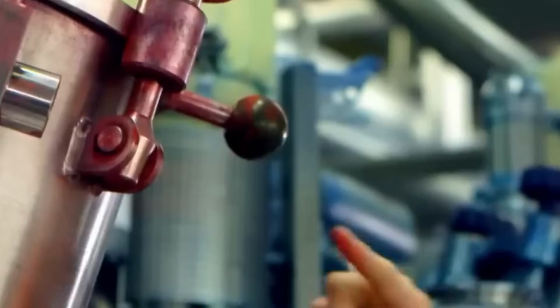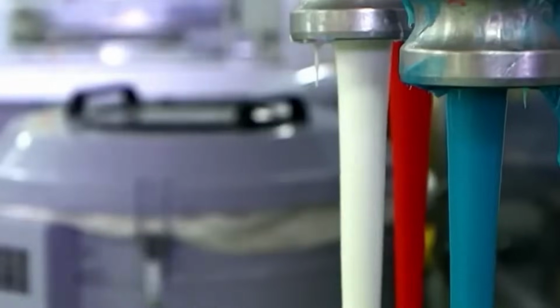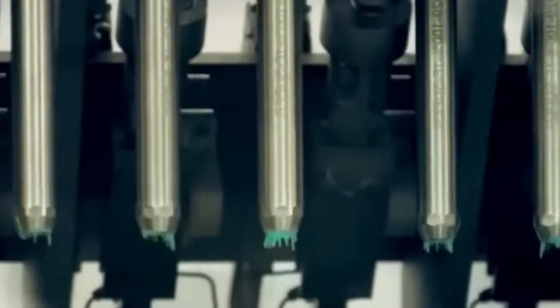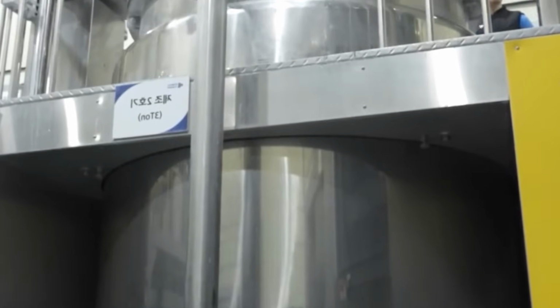During production, the entire process is governed by a centralized control system. Each piece of equipment is connected through a SCADA network, allowing operators to monitor tank levels, batch status, mix parameters, and fill rates from an HMI panel. Ingredient weighing stations utilize barcode scanners and recipe control software to prevent cross-contamination and ensure formula compliance. Any deviation from programmed weight tolerances triggers an alarm and locks further processing.